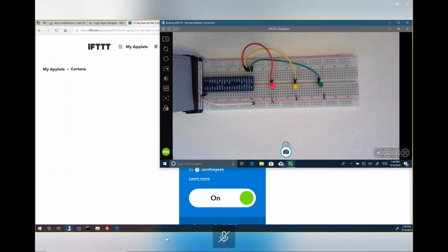the, what's the hotkey for a line? So the 3.3 volt wire here is going to this rail, which is providing power to all of these resistors, which are in turn providing power to the LEDs. And then the cathodes from the LEDs are connected to their respective ports. Since the outputs from the LEDs are connected to the ports, they're going to be blocking the connection when they're high, set to 1, but they're going to be allowing the connection when they're set to 0. So that's why low is going to turn them on and high is going to turn them off.